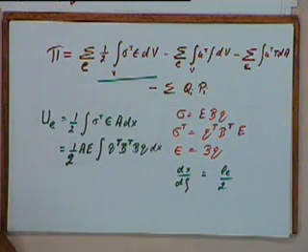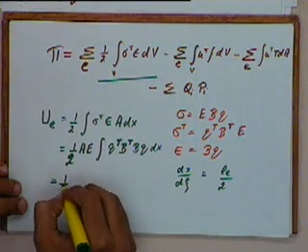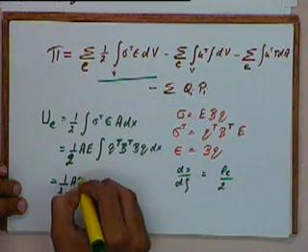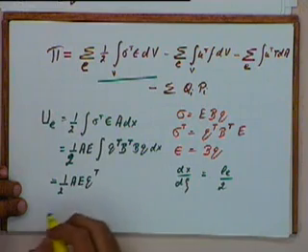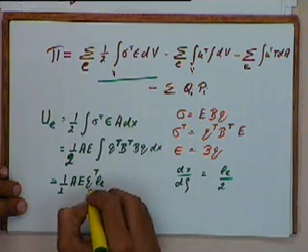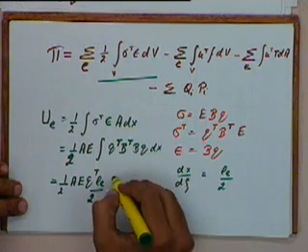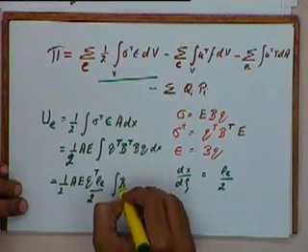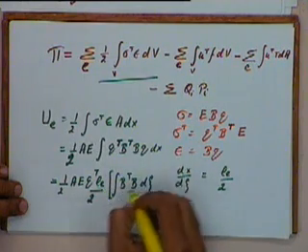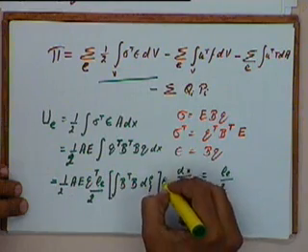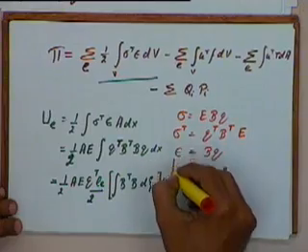Q transpose is of course a constant. So, I will get this to be equal to half of A E Q transpose. LE by 2 is again a constant, so I will get LE by 2 into integral of B transpose into B into d zeta, and this whole thing is multiplied by Q. Let me just draw a line.